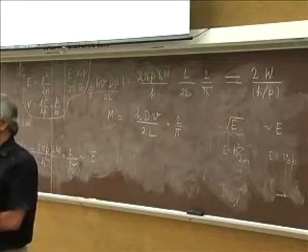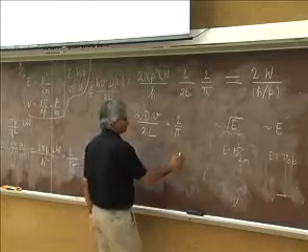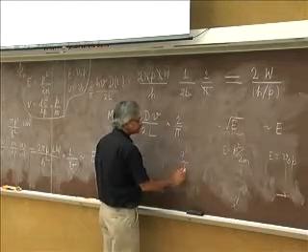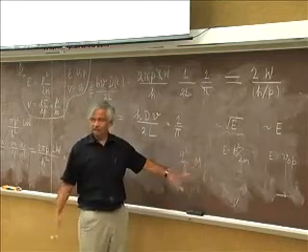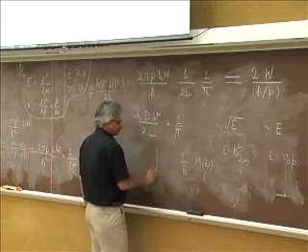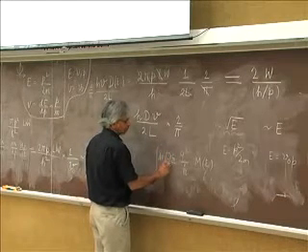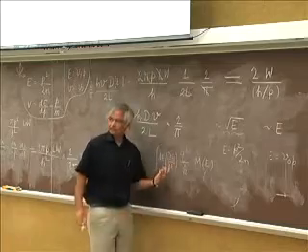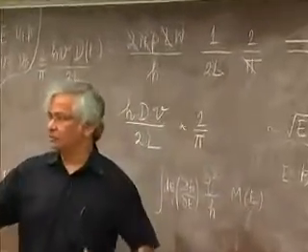And if you're talking of, say, the ballistic conductance, how much is it? I'd say, well, it's basically q squared over h times this number of modes. Number of modes at what energy? Well, over all energies, but then you have to integrate dE times minus del f0 del E, because all conduction properties tend to be averaged this way, right? For low bias, this usually works very well.